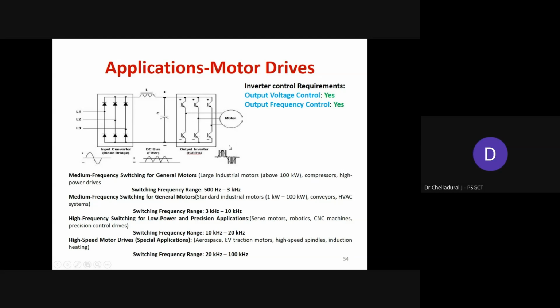With respect to motor drives especially, another important performance parameter related to the inverter is harmonic control. Harmonic reduction can be easily achieved by changing the switching frequency. Related to switching frequency, different inverter configurations are available based on the applications.